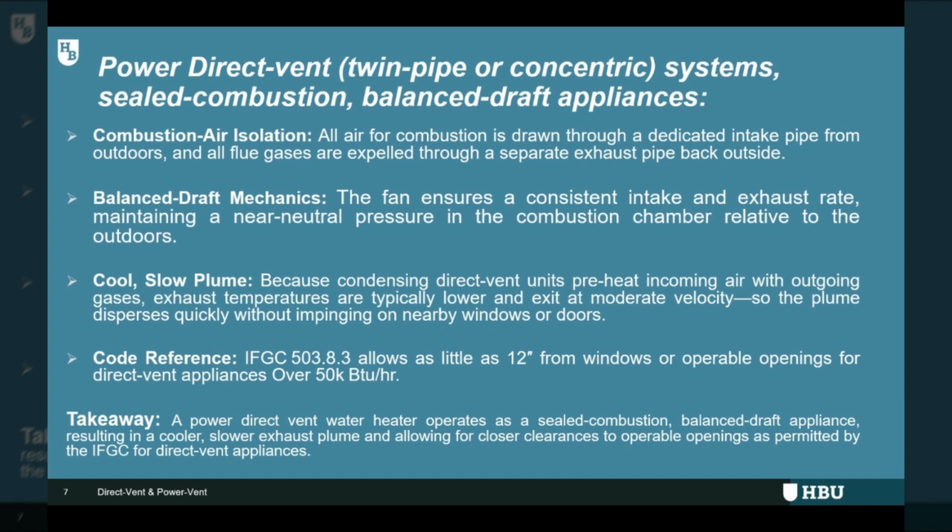The takeaway here is a power direct vent water heater operates as a sealed combustion balanced draft appliance, resulting in cooler, slower exhaust plumes, allowing for closer clearances to operable openings as permitted by the International Fuel Gas Code for direct vent appliances.